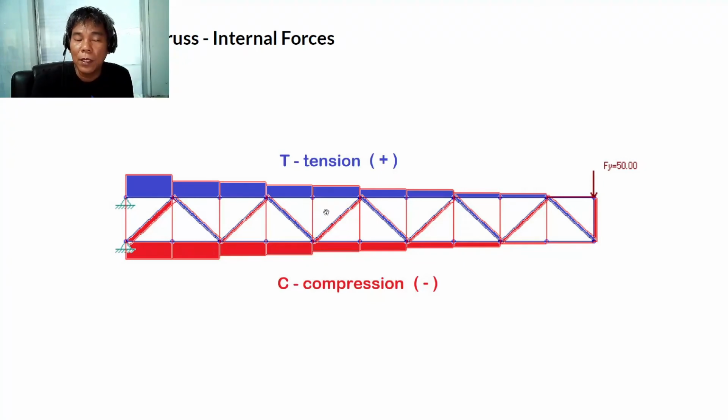So the forces in the members are internal forces. The web members, except the verticals that carry load and are zero, are alternately in tension and compression. Tension throughout the top, compression throughout the bottom, and the web members alternate between tension and compression.